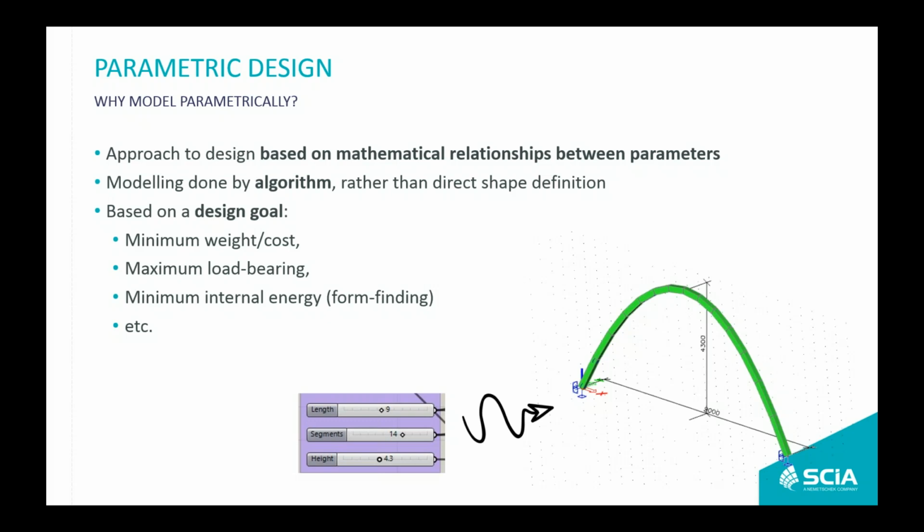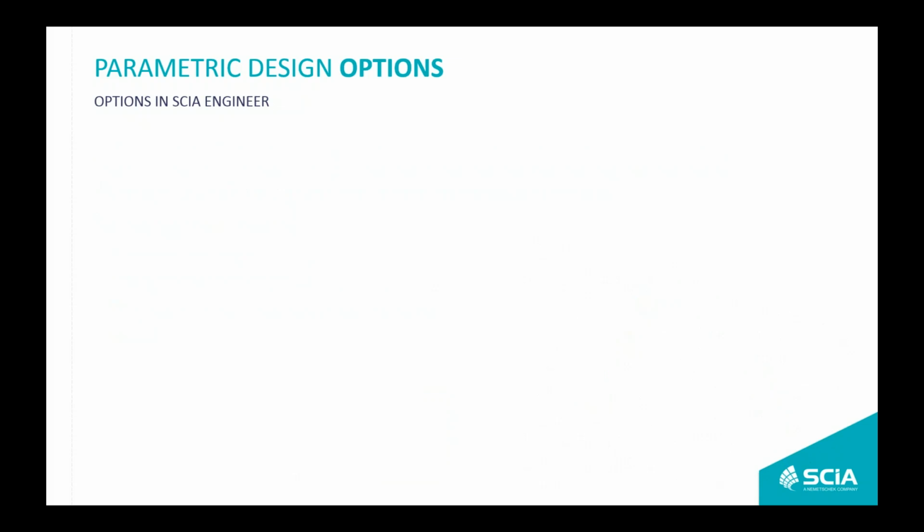In most cases, it's modeling of structures that have too many members to be efficiently modeled by hand due to some fancy or non-regular geometry, or we want to have some optimization loop, let's say finding the maximum load-bearing capacity while keeping the self weight or the material consumption at the same level. There might be multiple criteria, and the parametric shape is optimized based on those.